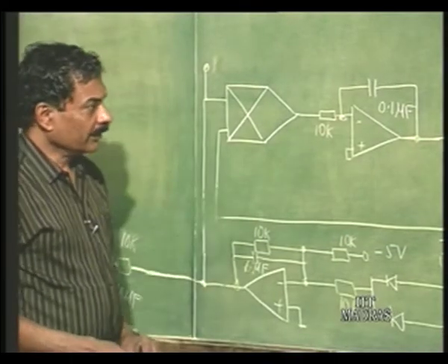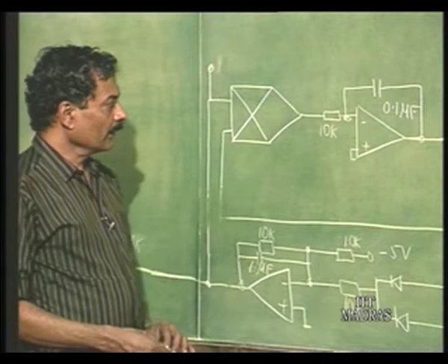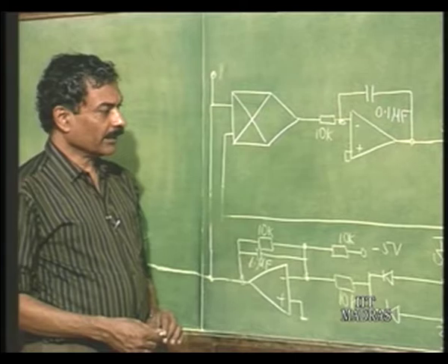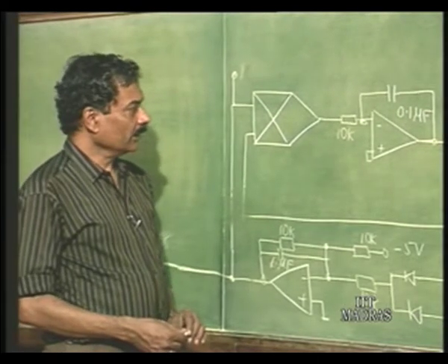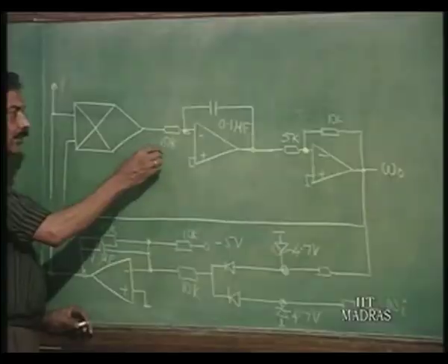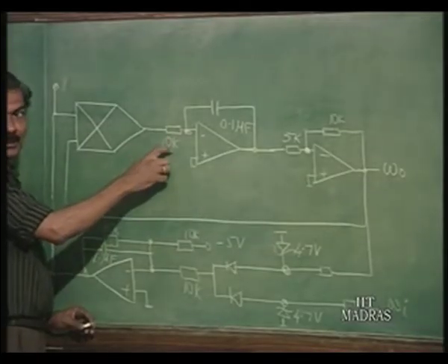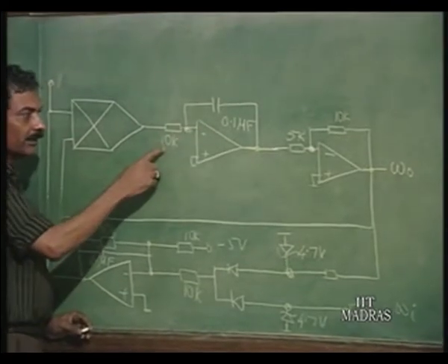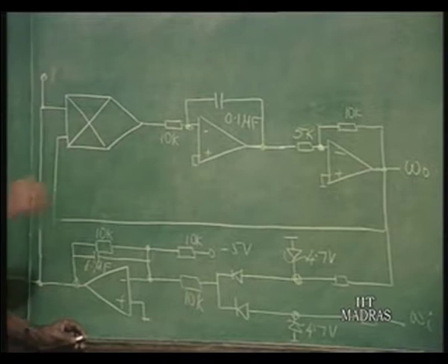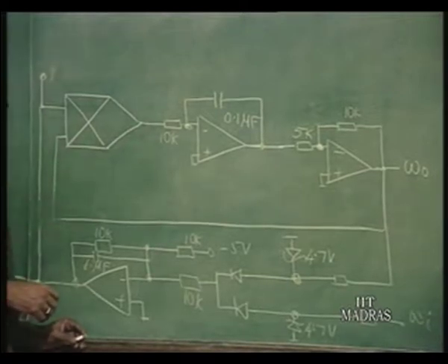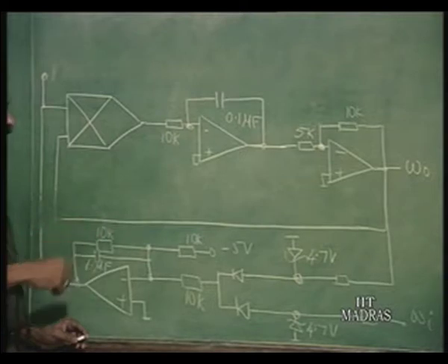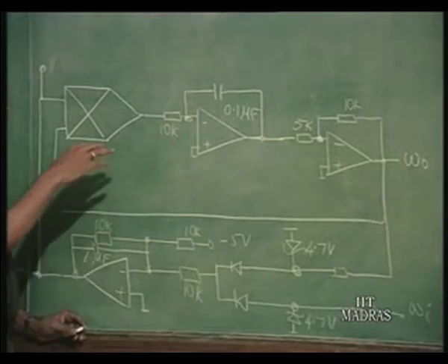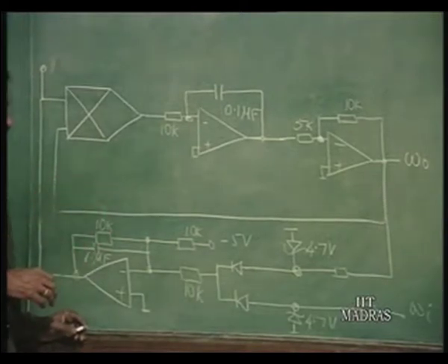Today, we will see something more about the phase lock loop. The phase lock loop that I have designed here, which is going to be demonstrated, is exactly similar to what we did earlier. Only thing is, it is oscillating at a lower frequency. Earlier we had put 1K and 0.1 microfarad. Now I have put 10K and 0.1 microfarad, so that the free running frequency is one order of magnitude reduced, because these op amps are such that the waveform that you get as a square wave was not good at high frequency. I had made it operate at lower frequency for ease of demonstration.